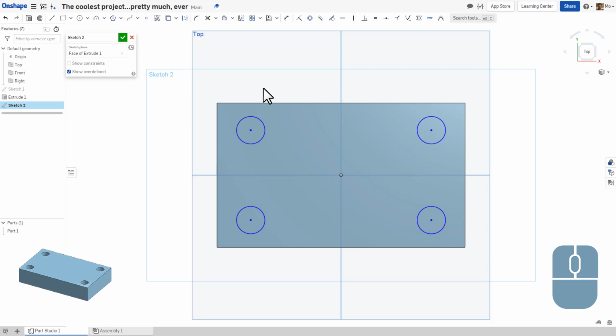Very cool. All right. So, last thing that we need to do, well, with any sketch, we need to make sure that we constrain in all ways, right? And that means adding dimensions. We don't want to leave this decision of how big these circles are based just on how close we got with our eyes, right? So, if we choose the dimensioning tool, and we come down here, I want you to click on the center of the circle.